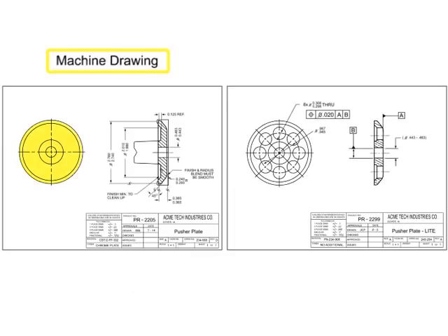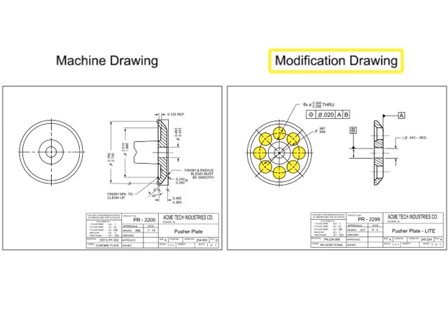As with a machine drawing made from a cast, modification drawings are created to add, remove, or rework details that result in a new part. Only the dimensions or other information required to alter the part into its new configuration are documented. Modification drawings also incorporate mandatory changes, for example, safety, reliability, or application extension into existing delivered equipment. This type of drawing can also be referred to as a make-from drawing.